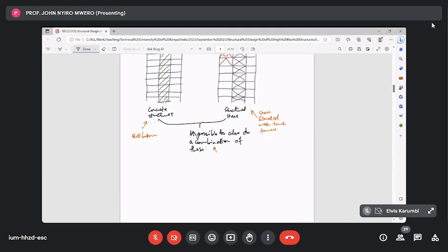So you can say, I want 5 hours fire resistance, and you'll find that you need a thicker concrete cover. And if these buildings had been provided with a good solid concrete core, the thought is that maybe they would have stayed a bit longer and people would have had more time to evacuate. Maybe not everybody, but a big number of people would have been saved.